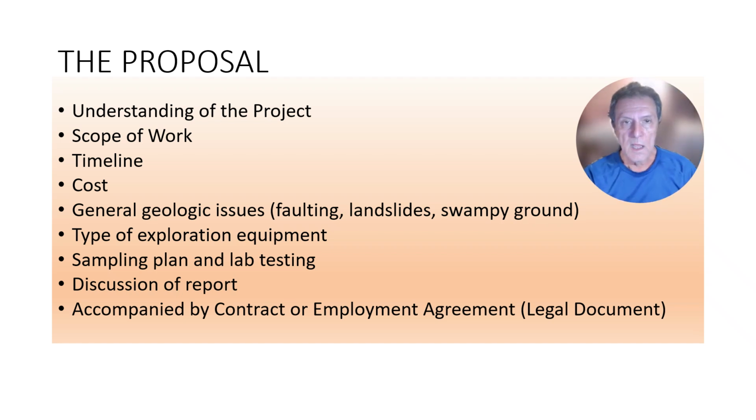You want to have an understanding within the proposal of what the major and general geologic issues are: faulting, landslide, wet ground, liquefiable ground, etc. You want to let them know what type of exploration equipment is going to be used. Maybe it's going to be a backhoe, maybe it's going to be a drill rig. Maybe you can't use a backhoe because of limited access, or you have to go deeper than a backhoe will go. Maybe you cannot use a truck-mounted drill rig because of access issues. So point that out, indicate that, put it in your proposal.